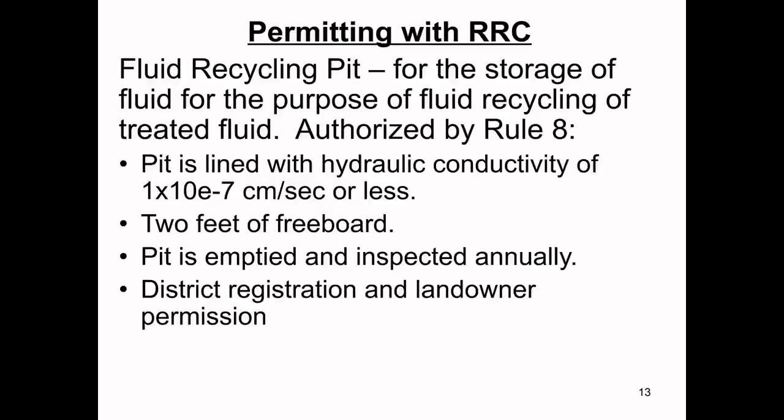Part of the regulations call for pits lined with hydraulic conductivity of 1 × 10⁻⁷ or less, 2 feet of freeboard, and they like to see the ponds be double lined with a leak detection in between.